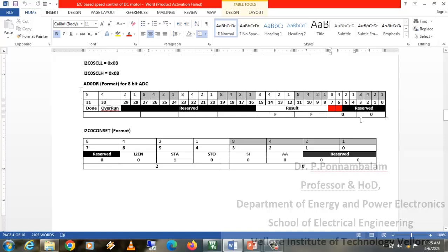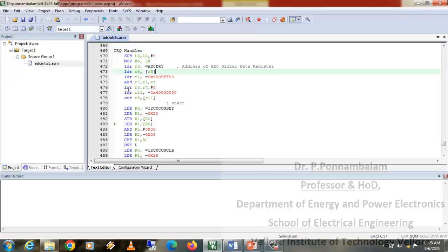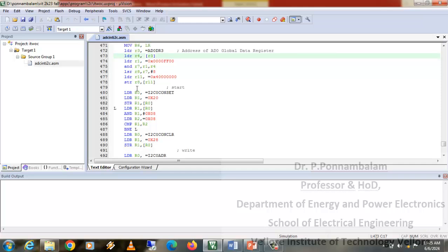The 8-bit value should be available in the units and tens, so if it stays here, these zeros will add to the value and give you wrong data. To avoid that, we bring it to the units and tens with LSR R8, R7, #8. Then I move the shifted value to memory address 40000.